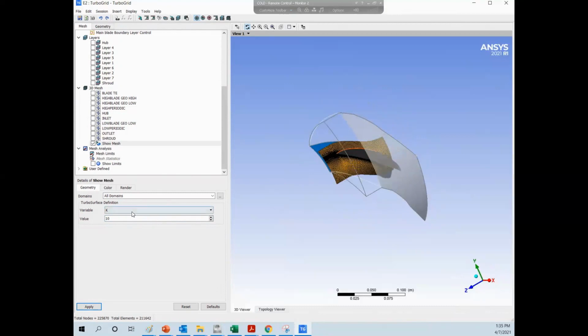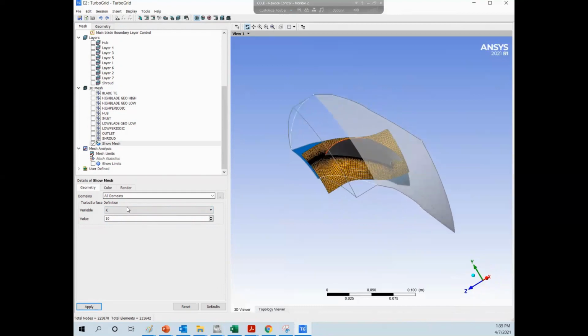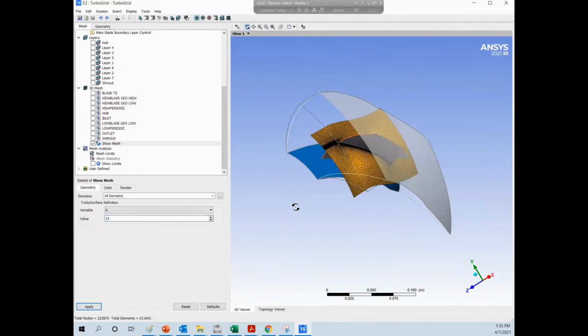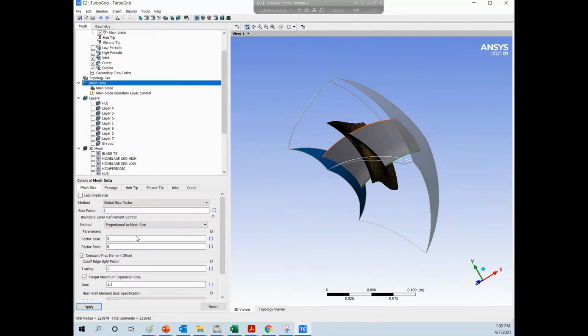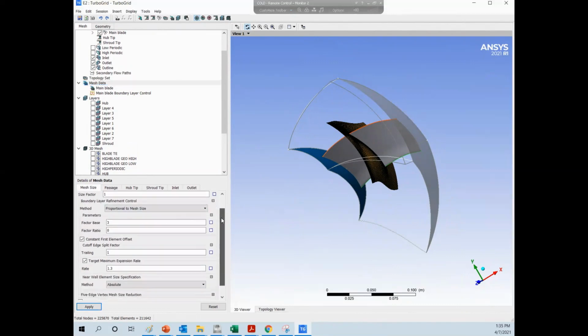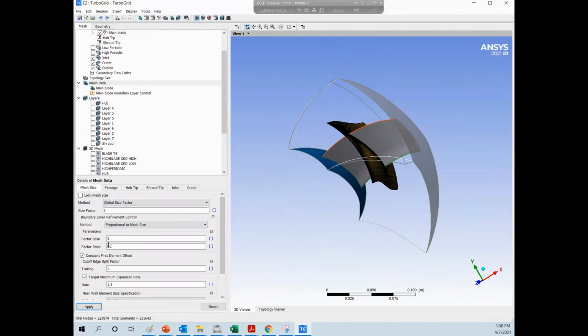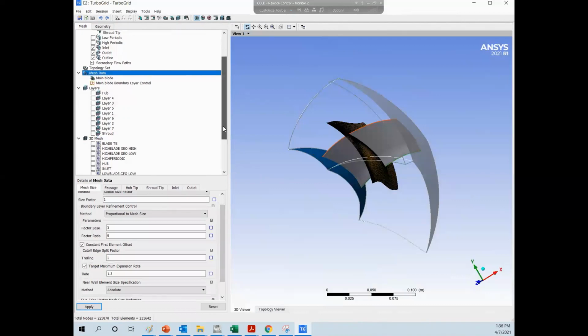And you have a quite good quality mesh. And in the back, at the trailing edge, it's fine enough to capture all the vortices behind that. So I'll just go with the default, which was 15, which is roughly in the center, and I'll stick to it. Sometimes you can play with parameters to make it, for example, a little higher quality, mostly for the quality of the cell. When you go to the volume mesh, you can play around with these variables and maybe change 3.4 to improve the mesh quality.